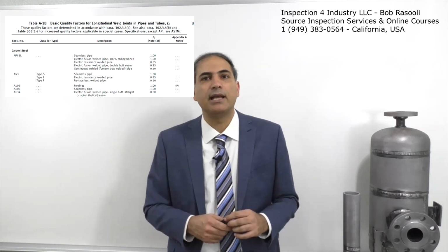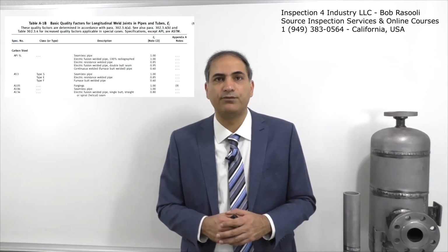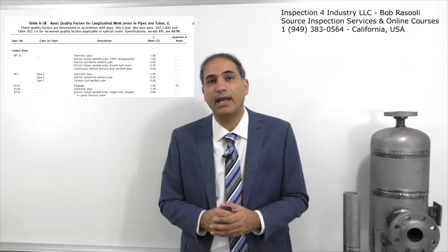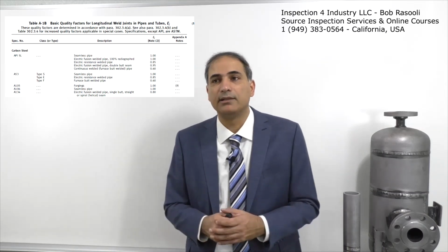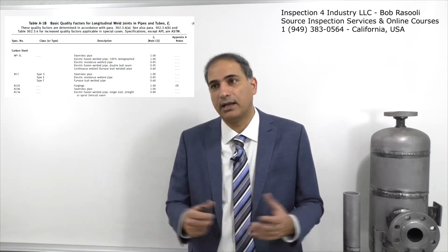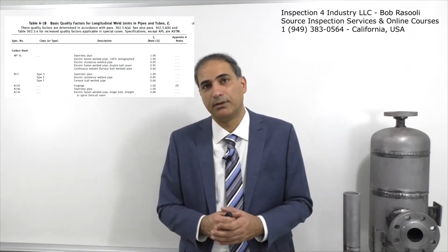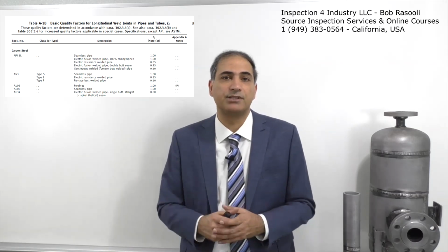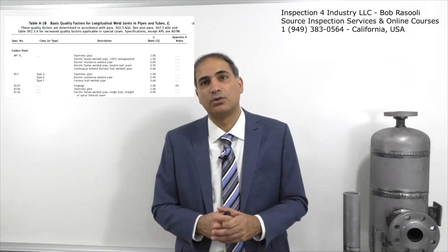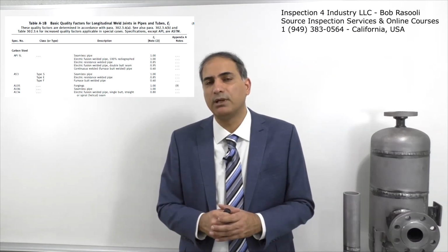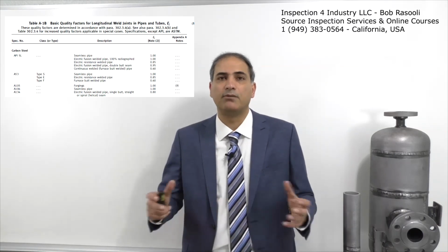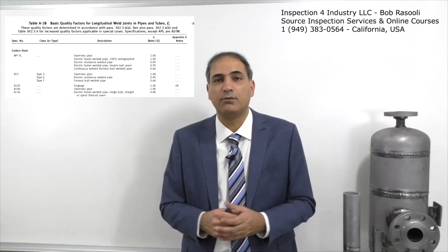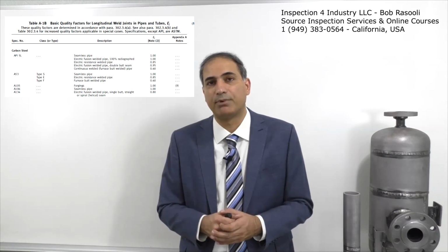And then you have an E value in this design formula, which is a quality factor, and it's addressed in the A1A table for casting pipe and the A1B table for the regular pipe, welded pipe. I mean the pipes that are made by a process other than casting. So different tables are used. We don't normally use casting in process piping. By the way, there might be old cast pipe still existing in some refineries. It's used for the sewer system, yes, but not for a real process piping system.